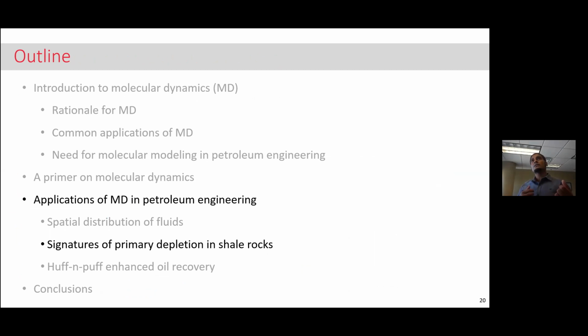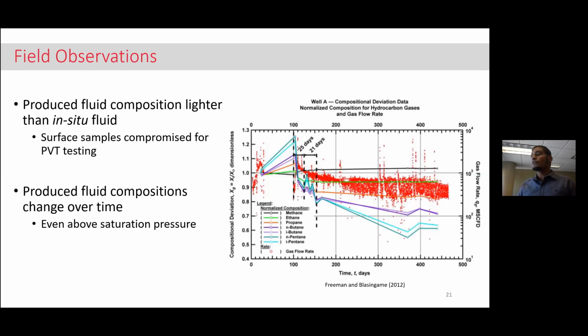It turns out that whether the molecule is adsorbed or free also controls its mobility. Something that we've known for an extremely long time is the fact that even at pressures above the saturation pressure, if you're talking about an oil reservoir at pressures above the bubble point, or a gas reservoir at pressures above the dew point, in conventional reservoirs, we expect that if we're producing at pressures above the saturation pressure, the produced fluid composition should not change.